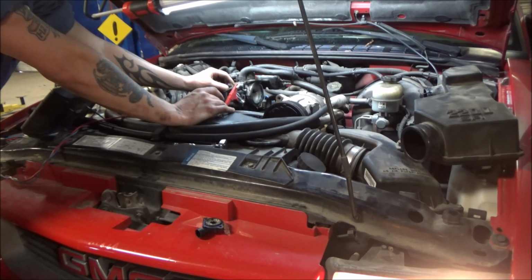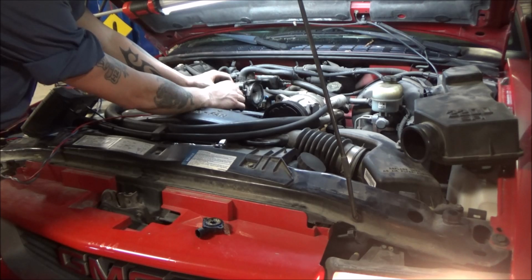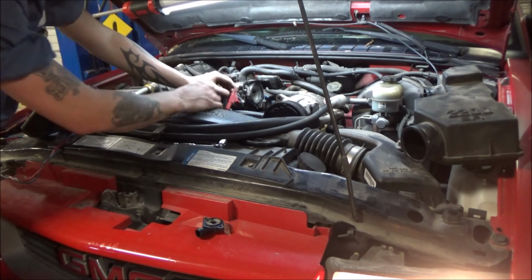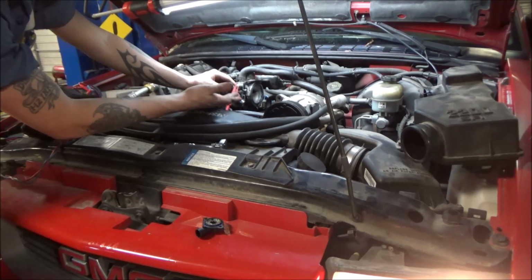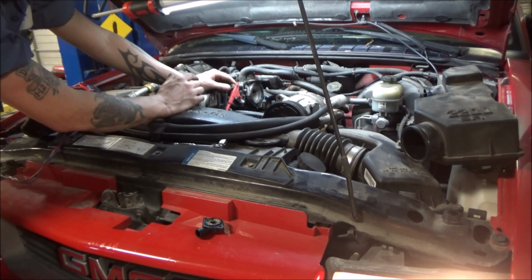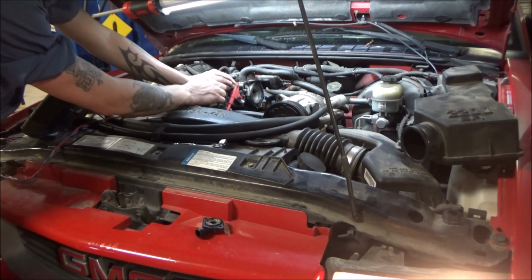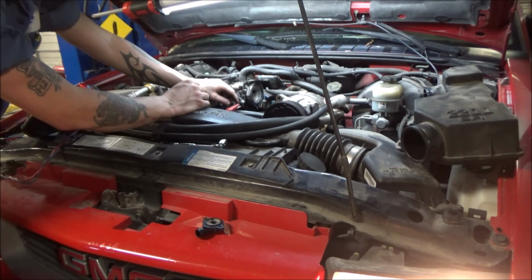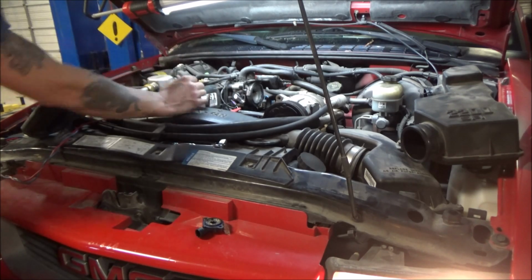So that being said, I think I'm just going to use a test light for this, guys. I know some guys will probably disagree with this, but I've had no issues with doing this in the past. So what I'm going to do to execute this test is take a simple incandescent test light. You can also use an LED for this test. I'm going to attach that test light to battery positive, and I'm then going to touch this test light on this pin, and we're going to see what the reaction is on the scan tool. So let me get that test light, and I'm going to get you guys focused on the scan tool, and we'll do that.